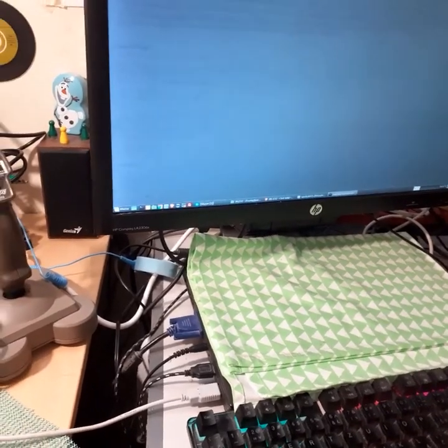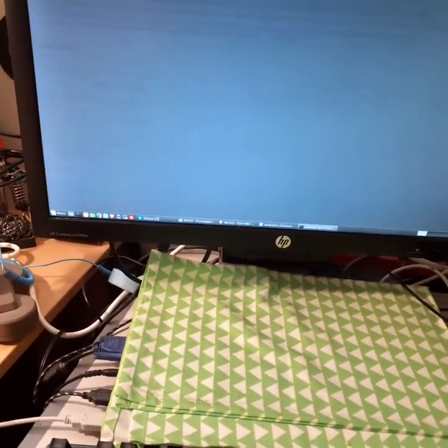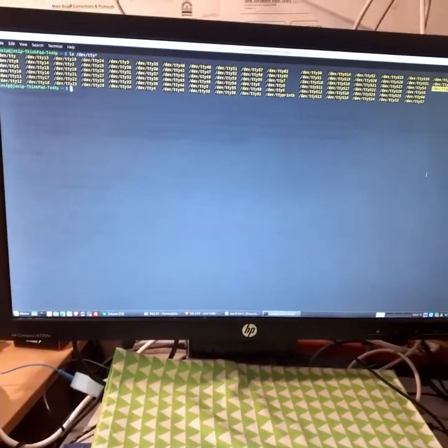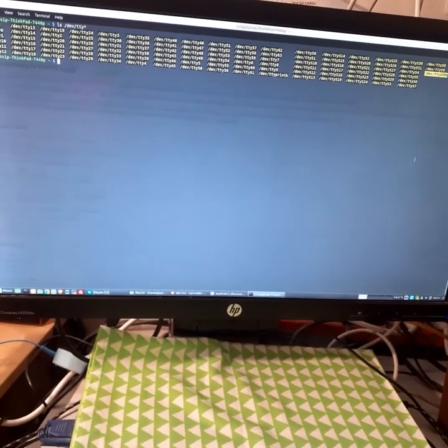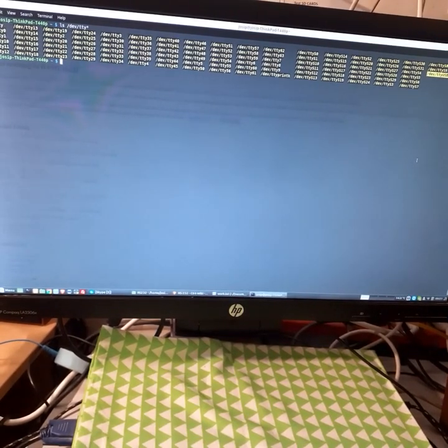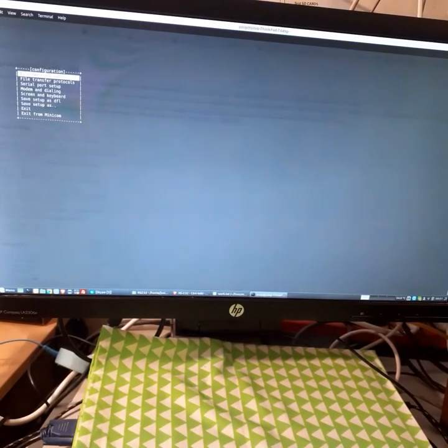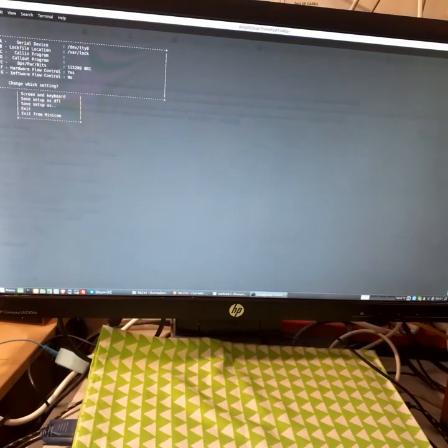modern PC. I don't know how much you see here, but we will do, do we have our device here. We will open Minicom and we will set serial port on the TI USB 0.